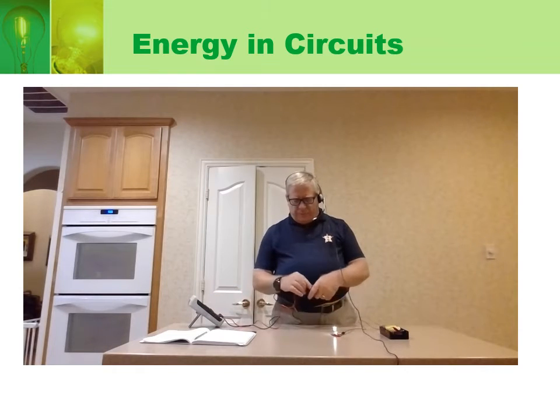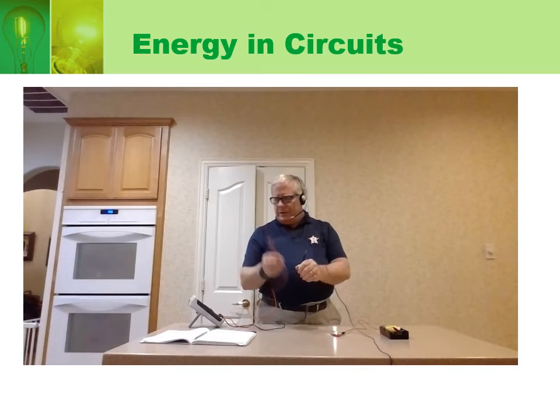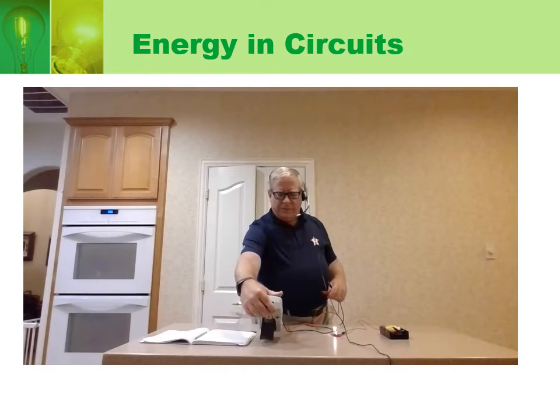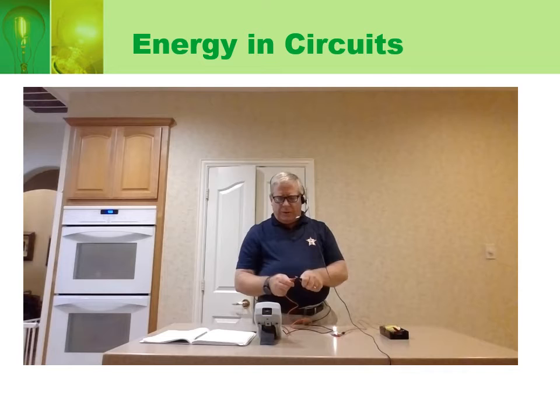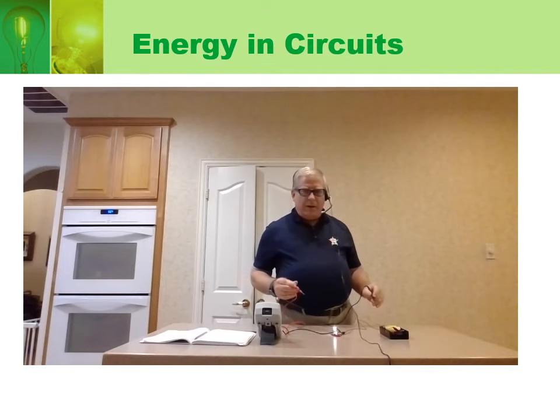And then I have a wire here, and that's going from the positive side of the battery over through here, in through the light bulb, lighting it up, and then coming back here, and it goes back to the negative side of my battery. And what we're going to do today is measure the potential differences. That is the change in potential energy per coulomb of charge that flows from the black probe to the red probe. I know you can't see these numbers over here, but I'm going to read them out to you as we do it, and we can write them down and analyze them later.